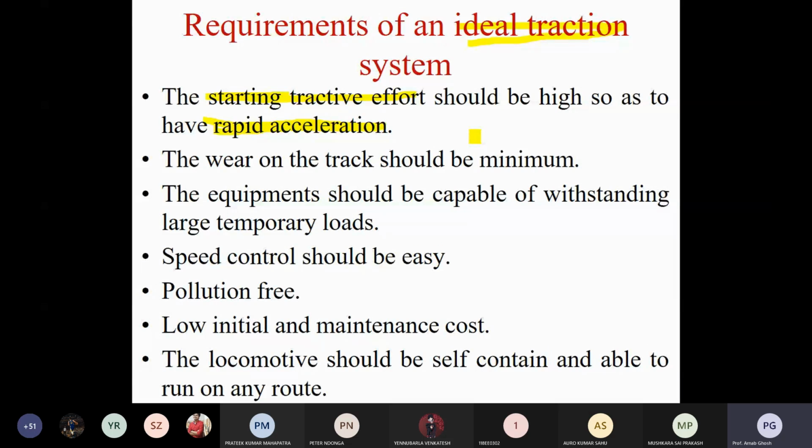Then the error passes through the controller, and the controller gives some response. We compare that with the repeating sequence to get the PWM. That PWM is passed through the driver circuit. Then you know that is the control of your power electronics converter. That's the basic concept.